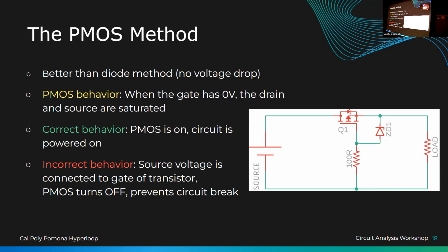Generally, it depends on the PMOS you use, I will say. If you're using a logic level transistor, generally the turn on region is about 0.7, 0.8 volts. That's like the curve you see on a graph. But some transistors even have lower or higher values. It just depends on the one you use. And each transistor has a voltage drop calculated by the internal resistance of the transistor. It's a really small R that's inside each one. But again, if you want to really know the specifics, you got to look at a data sheet. Then you get to the complicated zone of things.